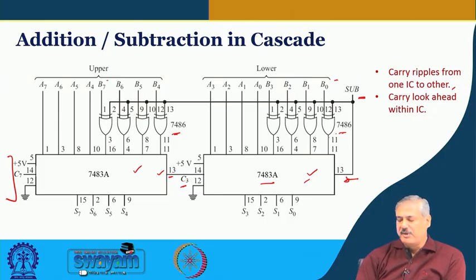So, this is 1's complement at the XOR gate output and 1 that is getting as input carry over here, right. And when it is addition, the sub will be 0. So, basically only B0 to B7 will come over here, no inversion will be done, and this is 0. So, this is normal addition that will take place.